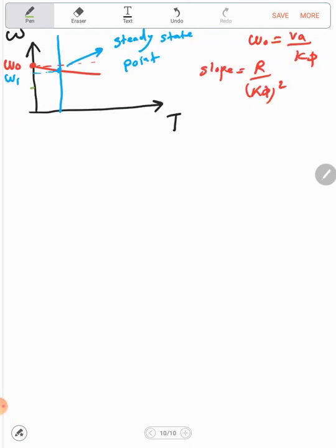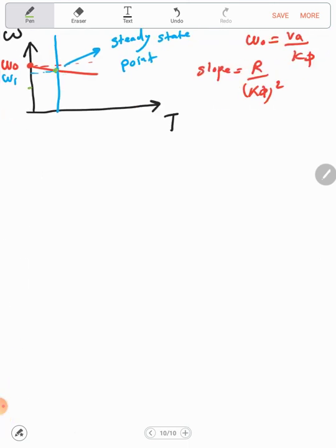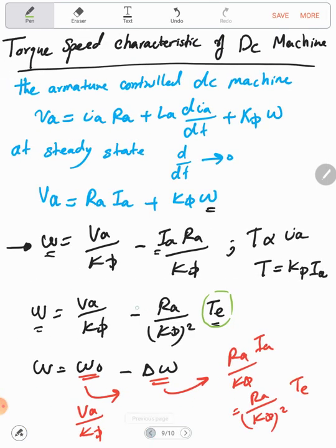The torque depends on the load. This is the point here when TE is equal to TL. So we cannot control the load torque in order to achieve the speed, because in general the load torque must satisfy a certain speed profile, and we must fulfill that. So looking for the speed relation here, we can say that we have three possible methods to control the speed.